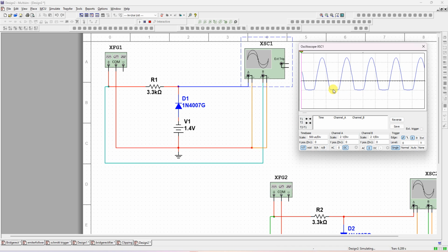So the negative voltage is clipped at minus 2 volts. You can see the input also. In this portion, all the input voltages less than minus 2 volts are removed, they are clipped off, and only voltages above minus 2 volts are coming here.